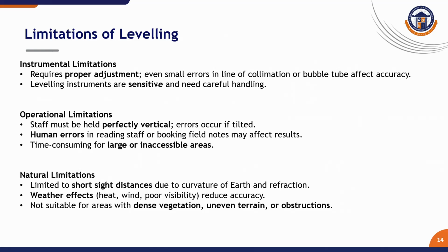Limitations. Leveling, while powerful, has its limitations, and instrumental limitations include the need for perfectly adjusted instruments. Even a small error in the line of collimation can cause a significant error over distance. These instruments are also sensitive and require careful handling.